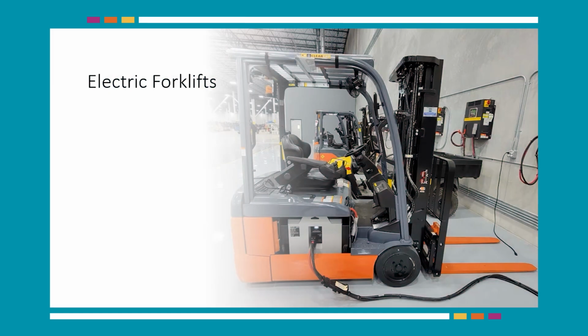Electric forklifts operate the same as propane forklifts. However, there are different hazards when charging a forklift battery. Lead-acid batteries are very heavy. Any equipment used to move batteries should facilitate easy movement without the need for manual lifting or awkward body movements. Review proper lifting techniques as well as any limits on the amount of weight that should be lifted by one person.